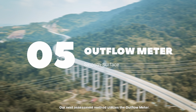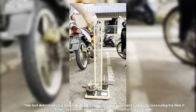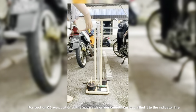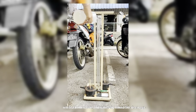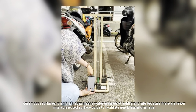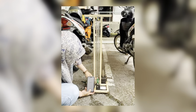Our next assessment method utilized the outflow meter. This test determines the water drainage capability of the pavement surface by measuring the time it takes for a known volume of water to escape under a cylinder. For section 05, we position the apparatus on our smooth surface, fill it to the indicated line, release the valve, and carefully time the drainage. On the smooth surface, the time metric means water escapes at a different rate because there are fewer interconnected surface voids to facilitate quick lateral drainage.